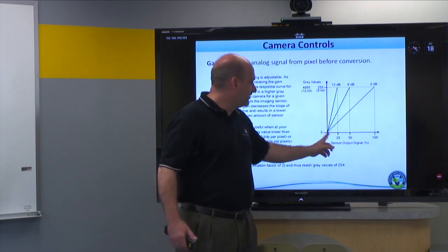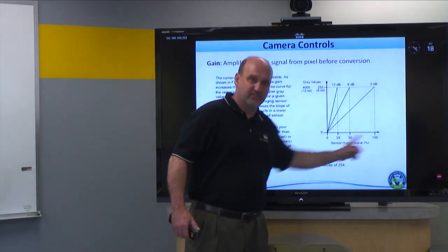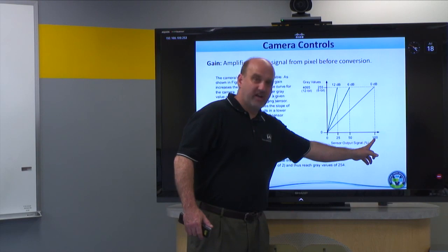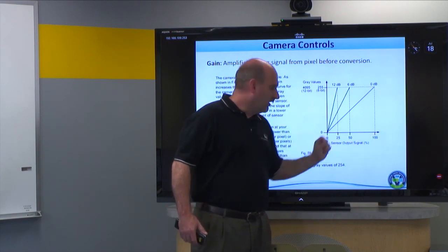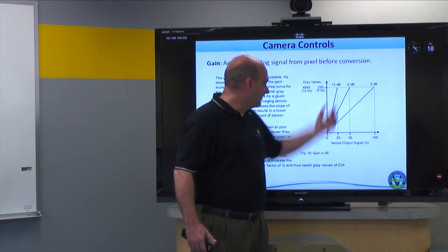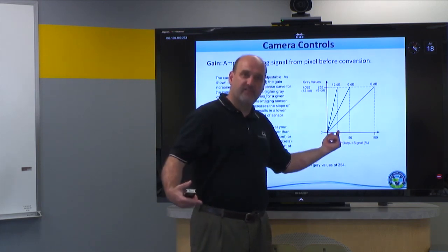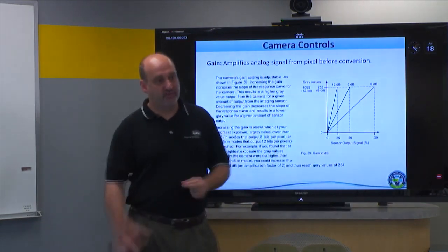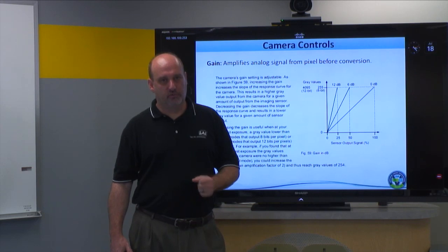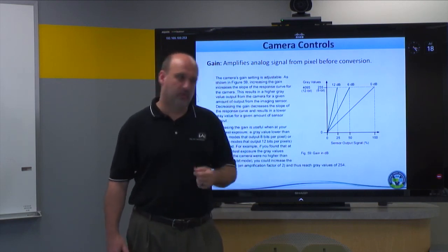Again, the dynamic range is the ratio between the light that's black and how much light it takes to saturate the imager. So at full well capacity, I have a very high dynamic range if I measure these ratios. But if I've only used 1/4 of the well and used 4 times the gain, then my curve is steep and the light range, the light it takes to saturate is now only 1/4. So the dynamic range is cut by a factor of 4 as well, since the noise floor didn't necessarily move in the camera. So it's important to recognize that, because a lot of our customers don't recognize that turning up the gain affects the dynamic range of the camera. They might think in terms of, well, I knew the signal to noise ratio fell, but they didn't necessarily understand the dynamic range fell.